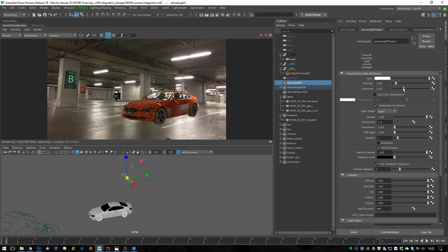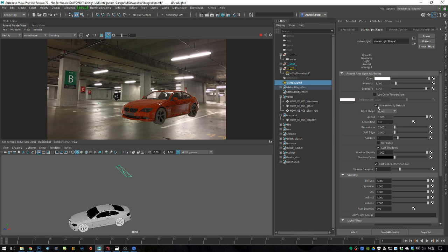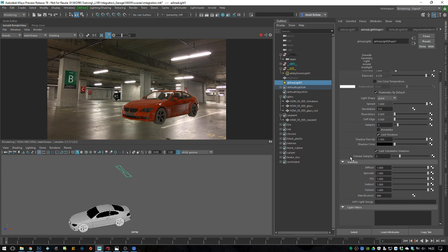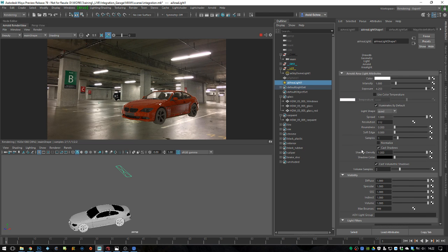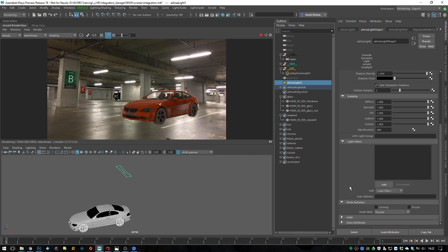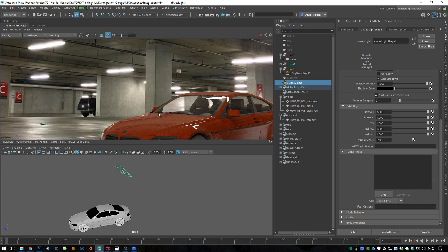And if you want to have a reference sphere, it does really help just to see how the lighting works. So you would create a normal reference sphere, and then you would just place it just to see the amount of lights you get. I can set the light to visible. Let's see if I can set it to visible. I don't think I can, unless they changed it recently. Normalize, cast shadows, cast volumetric rays. No, there is no way to make it visible. It's just currently for mesh lights. So you can see the light is now reflecting on the window here.